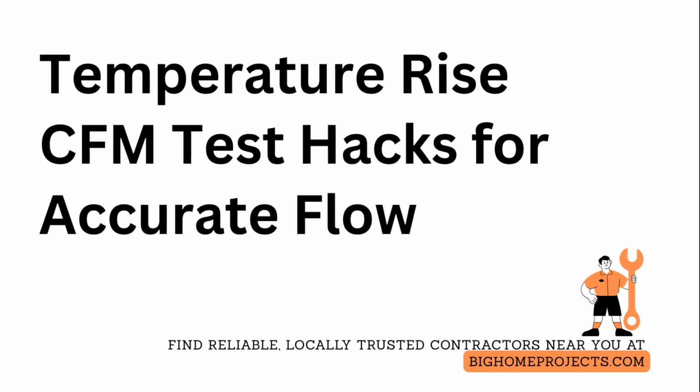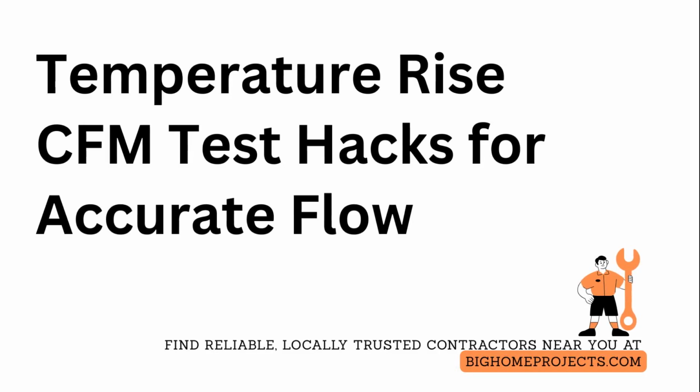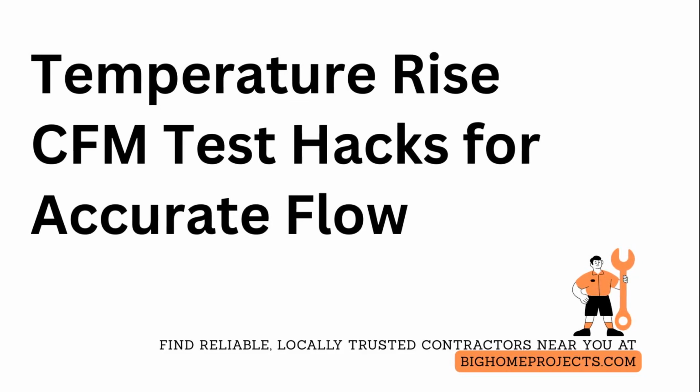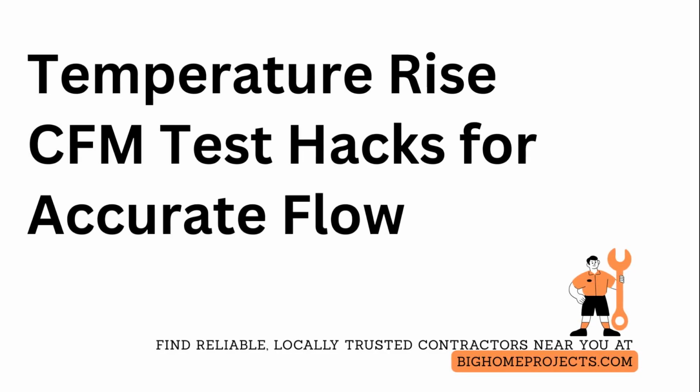HVAC temperature rise formula for measuring airflow CFM is simple. CFM equals the heat input in British thermal units per hour divided by the product of specific heat of air and the measured temperature rise. So get accurate supply and return temperatures, and you get reliable airflow numbers fast.